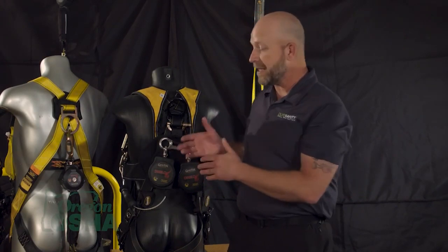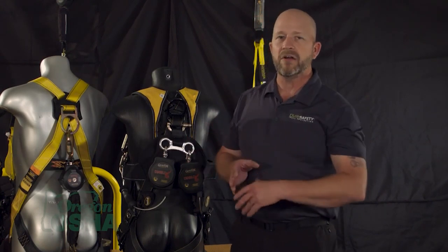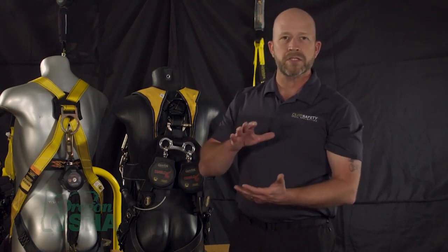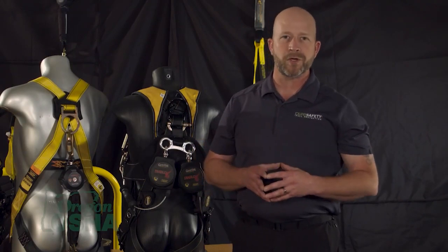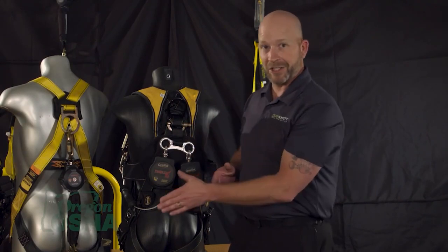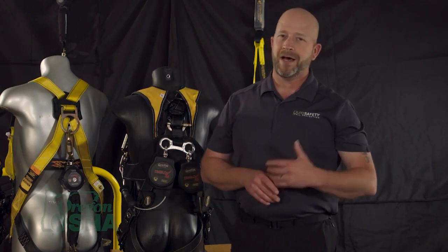However, just because you are working where you have an edge and that might be the device of choice, you still have to consider fall calculation and fall clearance, because if you're only 12 feet up in the air and this device requires more than that of total fall clearance, you still haven't protected the worker because, yes, it didn't shear on the edge, but they hit the ground. That's unacceptable. Not because of the law, because your worker hit the ground.